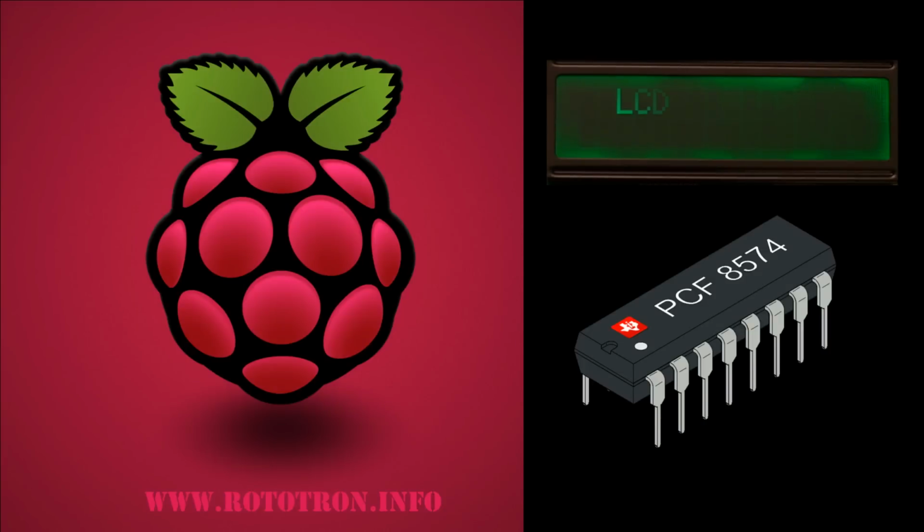This is the fourth installment from my tutorials on using LCD displays with the Raspberry Pi. It builds on my previous 3 videos, so I recommend you watch them first. This tutorial will demonstrate how to control an LCD display using I2C. We'll start with the PCF8574 I/O expander chip.